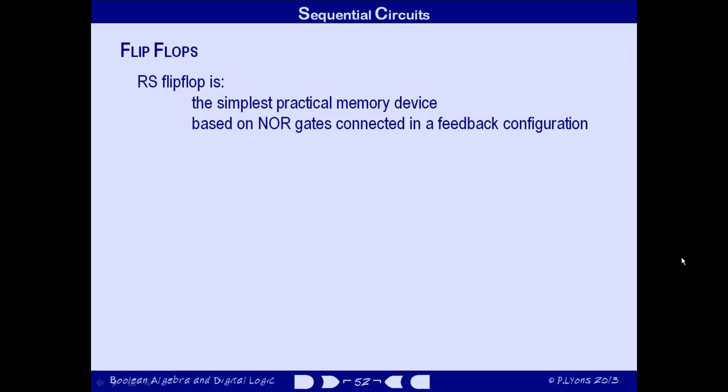A flip-flop should be capable of being loaded with a bit of data, either a 0 or a 1, and retaining that information until a new data value is loaded into it. Up till now, we've designed circuits by working through a standard sequence. English language description leads to truth table, leads to Boolean expression, leads to combinatorial circuit. This time, for a change, we'll start at the other end with the completed circuit and demonstrate that it has the desired behavior.